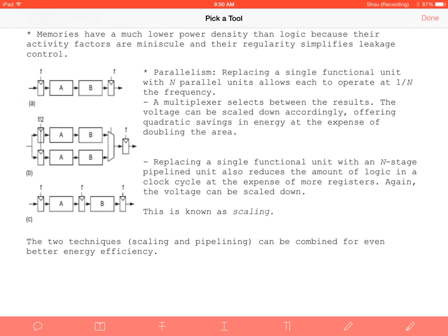So when you have multiple stages and multiple data paths, what ends up happening is you have these memories that you're trying to access, and you have to make sure not only that they're not switching very often, but that the value of the data is accurate. So if we have 2 different pieces of data in 2 different data paths, you have a value of X being operated here and here, and this data path switches it. What's going to end up happening is you have to ensure that this data path gets that value. So that's going to slow down the efficiency of your circuit.